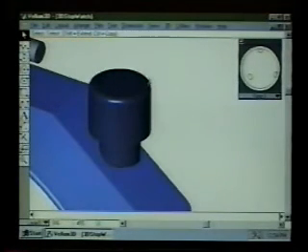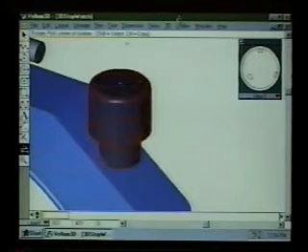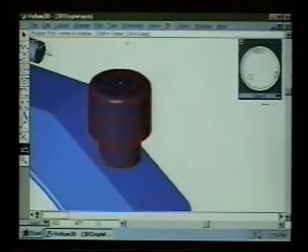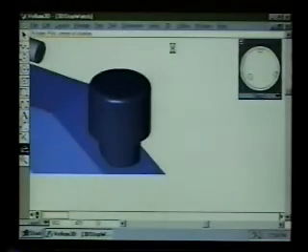So we can now rotate the part by selecting it, and we can go get the rotate tool. And we'll make sure that our plane is still front. Actually the plane is currently set to the slope face. We'll set plane to front, because we want to get the z-axis pointing in the same direction as the axis of rotation that we want to use.